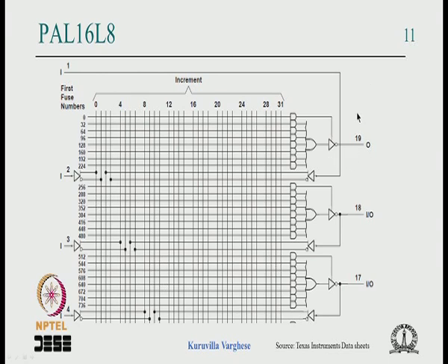Suppose you have Y to be implemented. Then you apply the De Morgan theorem to get Y bar, convert that into equivalent Y bar product terms, and implement it. Then you are implementing Y bar at this AND-OR gate, which is inverted by this inverter, and then you get the Y. That is how this was used. So this inverter itself is not a problem, because the complement was taken and implemented by the tools.